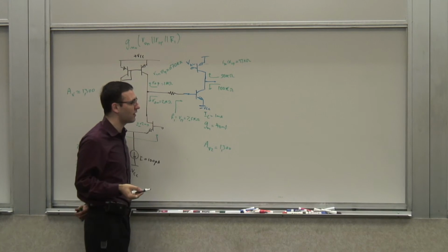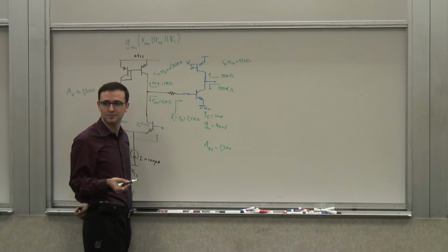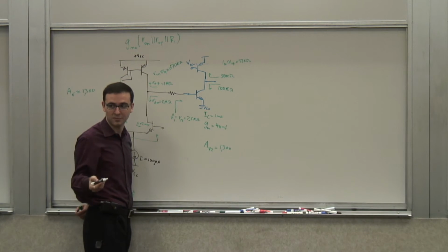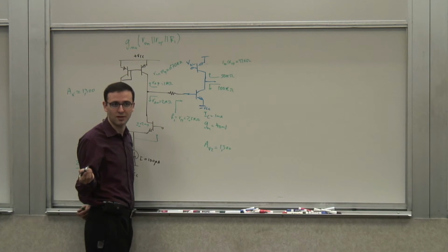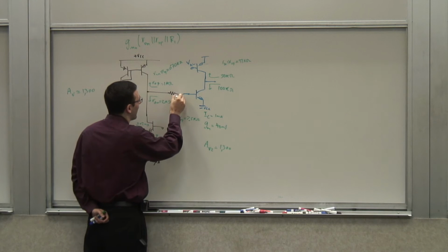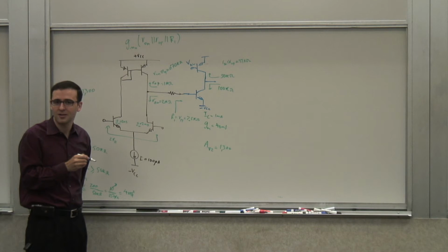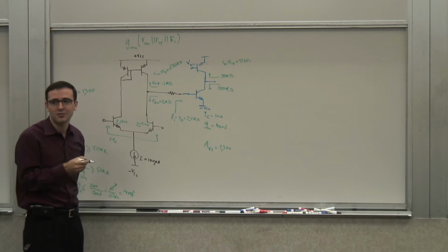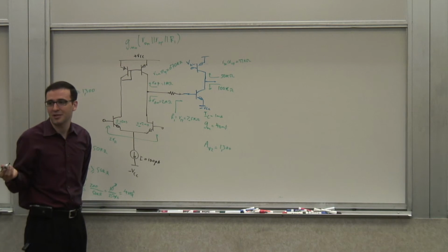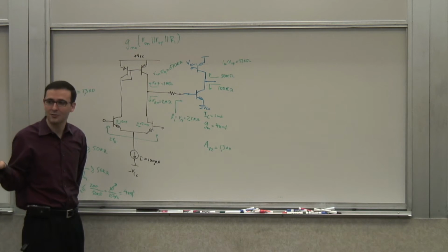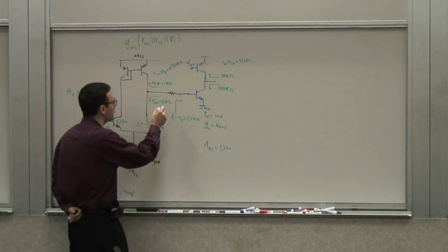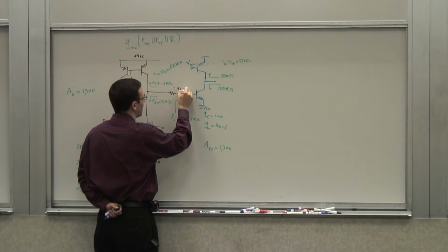So let's say the base current for this, what is the base current? If the collector current is 1 milliamp, divided by 100, divided by beta, which is 10 microamps, right? 10 microamps. And I want to drop how much? 18.6 volts on 10 microamps. So 18.6 divided by 10, which is 1.86, divided by 1 micro, which is 1.86 megaohm.